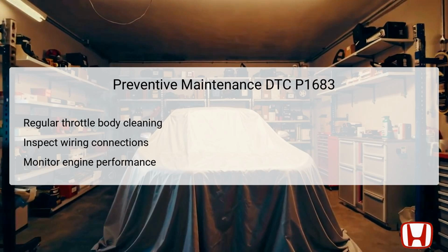Additionally, technicians should routinely inspect wiring connections for integrity, ensuring that there are no loose or corroded terminals that might contribute to erratic performances. Monitoring engine performance along with conducting regular diagnostics can aid in early detection of related issues before they escalate. Proactive measures not only enhance vehicle reliability, but also ensure the safety of the driver and passengers.